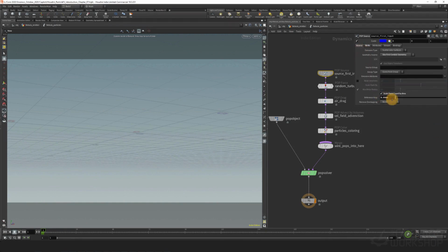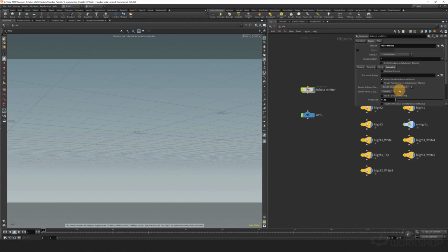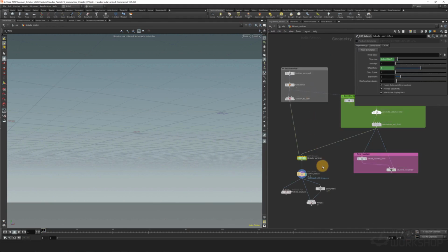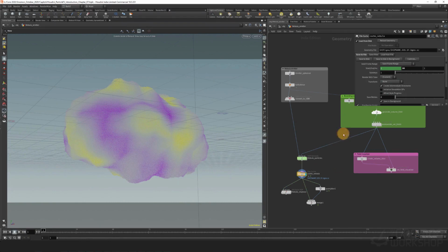Actually, inside the source we have 0.0085 for the reference area. To have a higher density, we go 8 times higher, so we go to 0.001. So we'll have a lot of particles this way. And about the particles, that's all. We have to do nothing else. So you essentially have to recache everything. The nice thing is that I recached everything before, so we don't have to write the particles back manually.